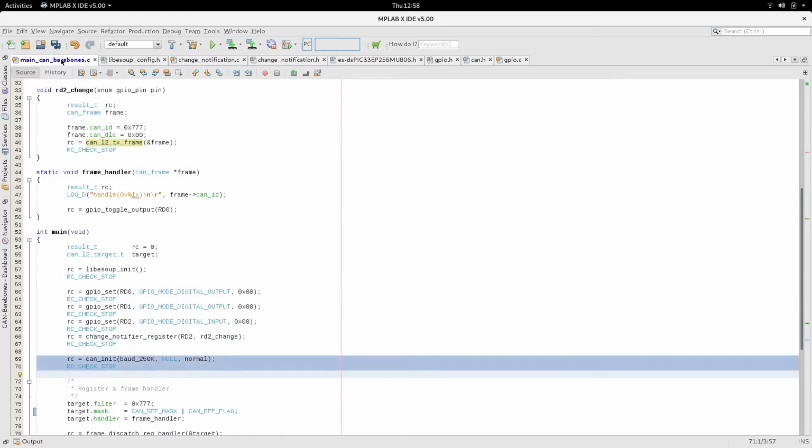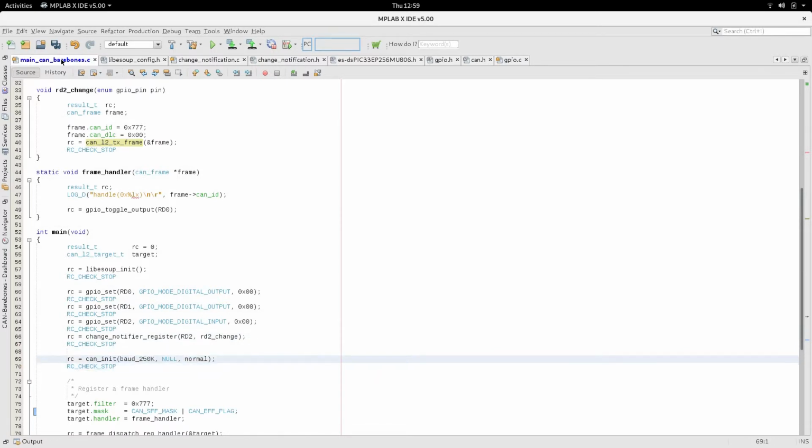We initialize the CAN bus. Now we're initializing a baud rate. So we'll take 250k. CAN bus is specified up to 1 megabit per second for, I think it's a 30-meter bus length. It was designed originally by Bosch for the automotive industry, so if you've got a 30-meter twisted pair going around a car, that's more than enough. 30 meters is more than enough for that environment.